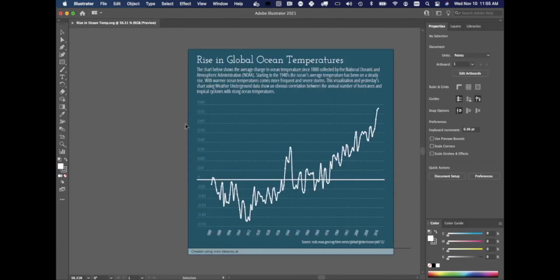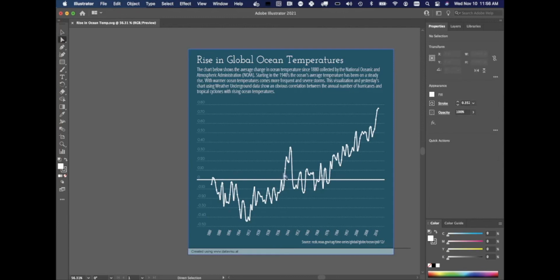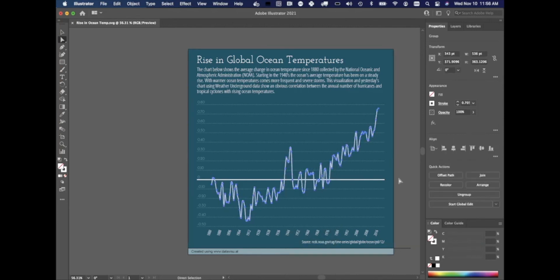So basically the only thing that I really care about is the line chart here. So we want to take this, bring it into a 3D rendering program, rotate it in a 3D formation. So it's kind of like just a 360-degree version of the line chart, which then we can send to a 3D printer. So I am going to just take that bit. So with the white arrow, do Control click. That highlights just the line chart.